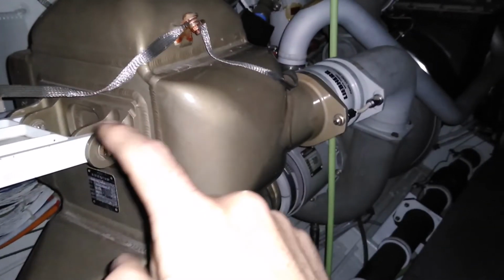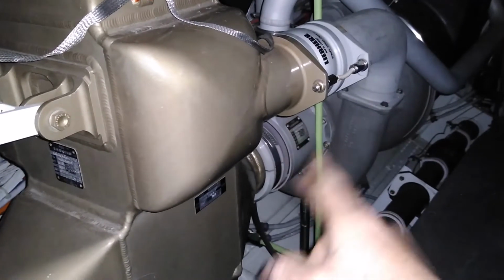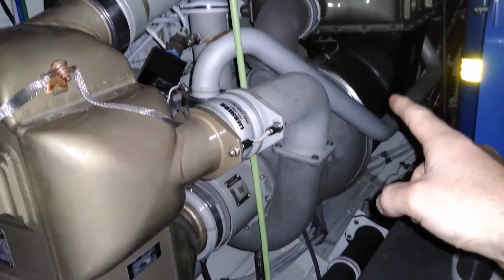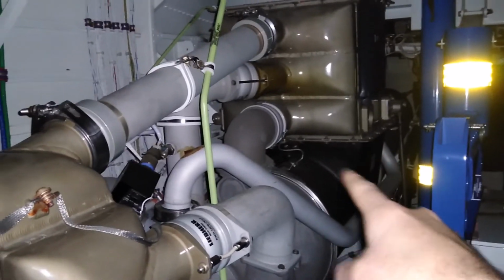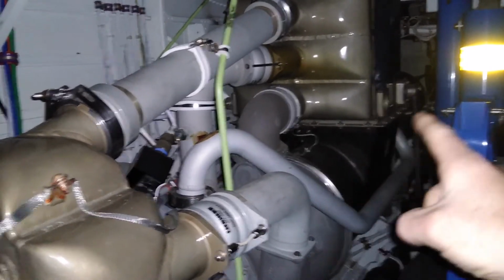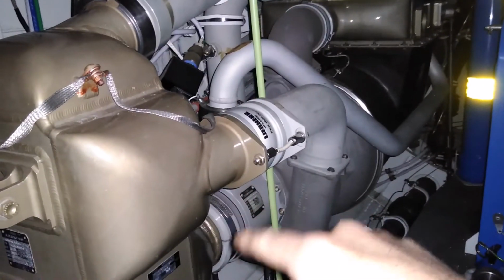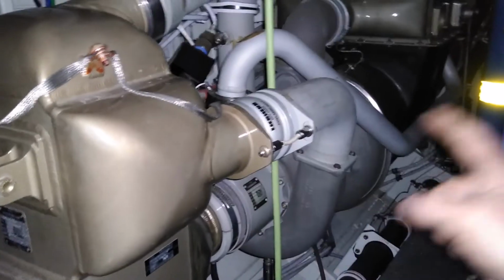Now that air that's already dried, but still high pressure, comes in through here, and it gets expanded in the turbine. And that air going through there, spinning the turbine, is what spins this compressor, which also spins that fan, which lives inside of the plenum here. The plenum is this housing here. The fan that takes over to create the airflow in case there's no ram air coming in is powered on the same shaft as the compressor on the turbine. It's powered by that turbine. And what powers the turbine is the bleed air from the compressor.